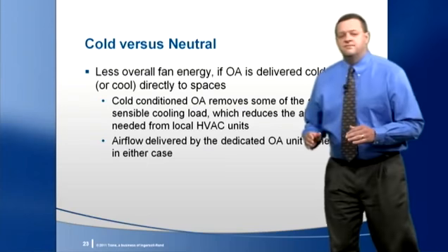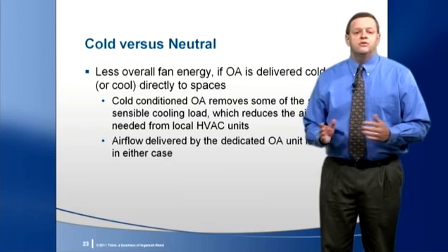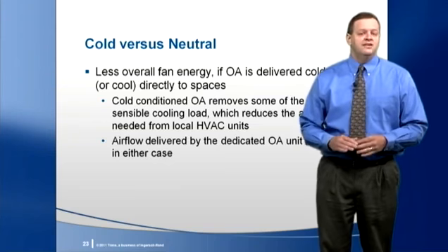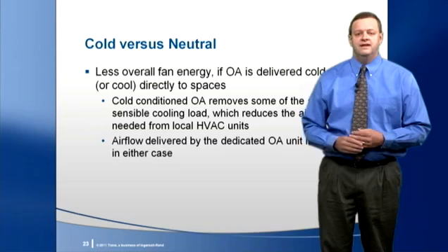One caution: if a space requires year-round cooling, the local unit serving that space may need to be sized based on the warmest temperature that will be delivered by the dedicated outdoor air unit.